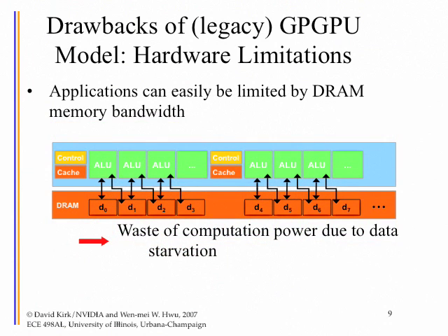Another difficulty is that in most of the previous GPUs, whenever you need to read from multiple data locations, even if two pipelines need to read data from the same location, there's no mechanism for them to save memory bandwidth. There's no way for them to piggyback on each other. So both of them need to go out and do the memory access.